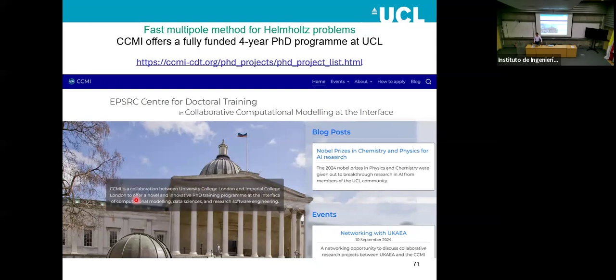What about adaptive methods? Are they implemented in the library? Adaptive methods. More specifically, for example, when you have a boundary element method solution and you calculate the error by element and you mark the element which contributes the higher error, so you refine the mesh there. Oh, I see. Okay, yeah.